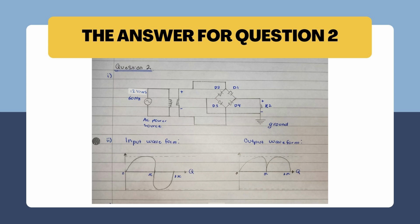From the drawing, you can see the transformer connected to an AC power source, which is 12 VRMS and 60 Hz. And on the right side, you can see the transformer also connected to the diodes, and we have to use 4 diodes. You can see the diodes also connected to the resistor and the ground.